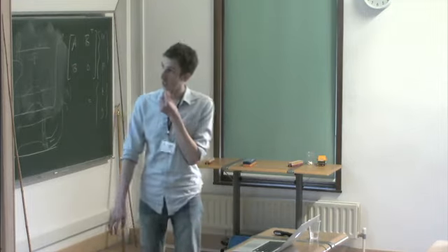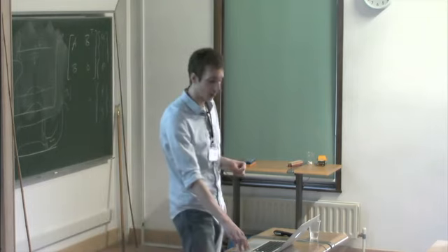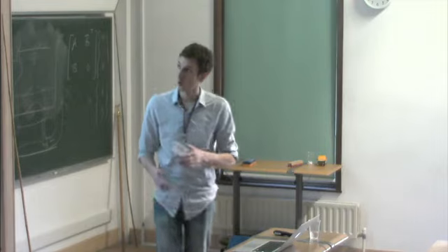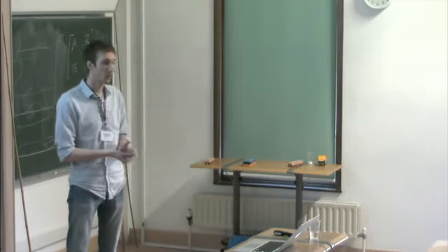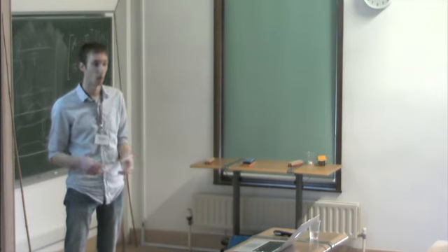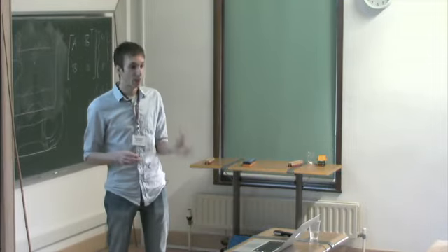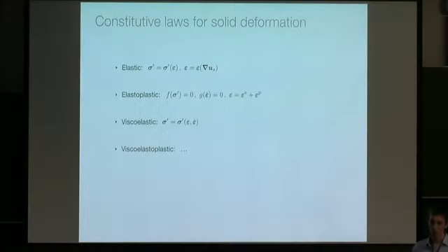Okay, so then we need a constitutive law for the solid. And here you can do a lot of different things depending on what your solid is doing. So of course you can have an elasticity law, in which case the stress in the solid is related to the displacements in the solid, or really the gradients of the displacements in the solid. Or you can have an elastoplastic law, or a viscoelastic law, or a viscoelastoplastic law. So Victoria covered more or less all of those bases yesterday. Today I'm going to focus on elasticity only.